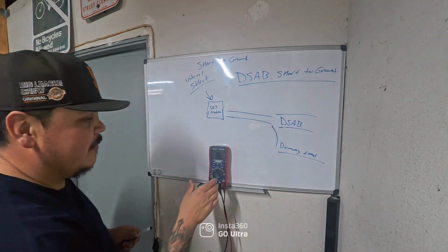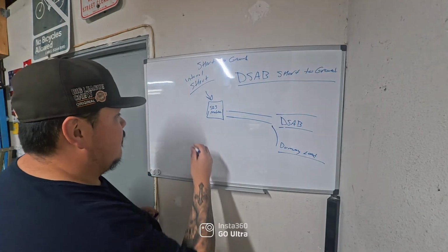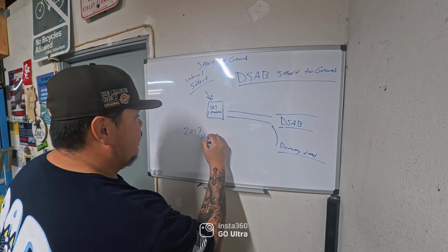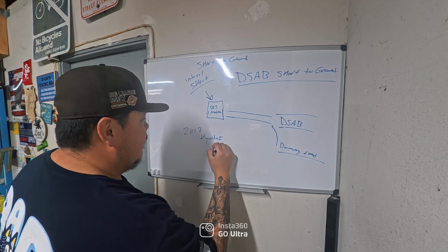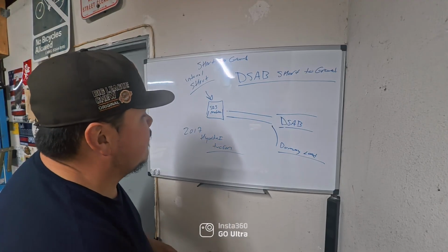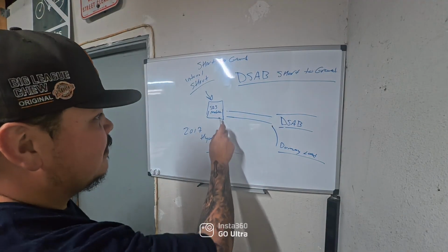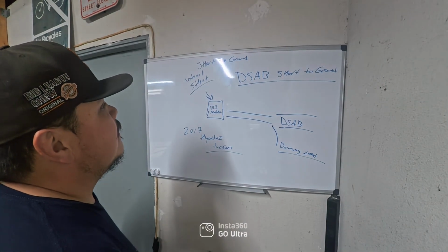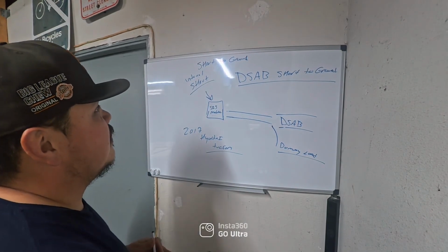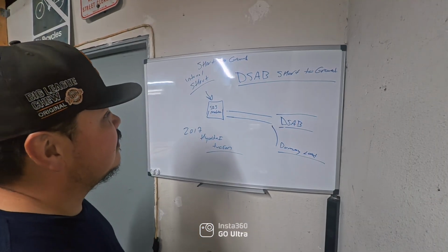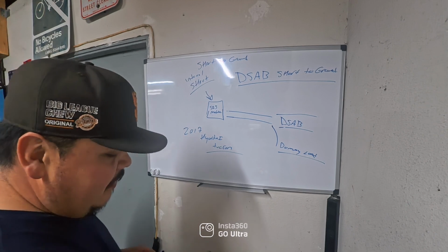This is pretty common with the 2017 Hyundai Tucson. So that's the way that I determine if the module is bad. Yeah, those are the two most common types of codes, short to ground or high resistance. Dummy load for sure.